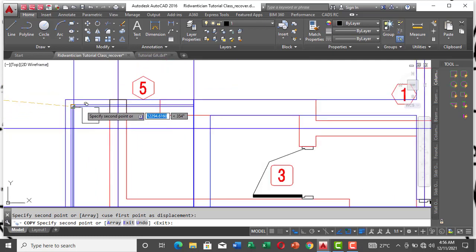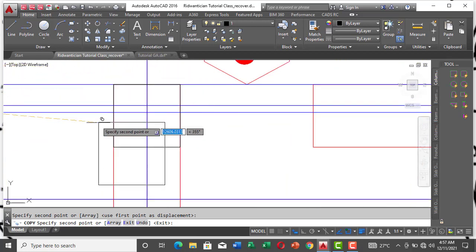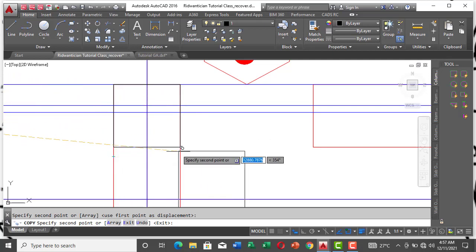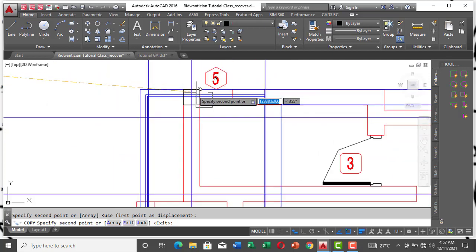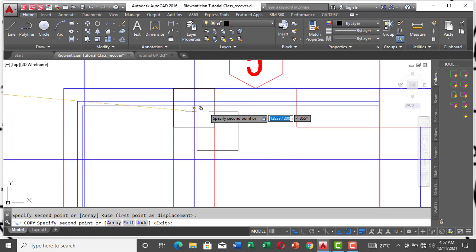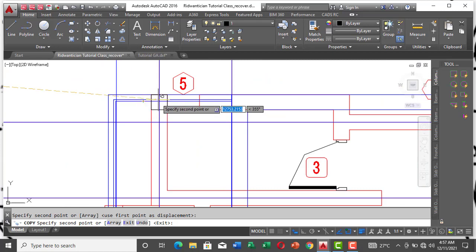because on the first floor what you have there is a terrace. Anything above here on the ground floor is a terrace. So you don't want this column going up, because even if you look at it here, you see that this blue line is not as long as this column. That is telling that whatever you have in this place should be like a guardrail. So you should not put a column that will go up until roof level. This will terminate at ground floor. It will not go up to the first floor. So this column will be coming from the foundation up to the ground floor, I mean the first slab, the ground floor slab.